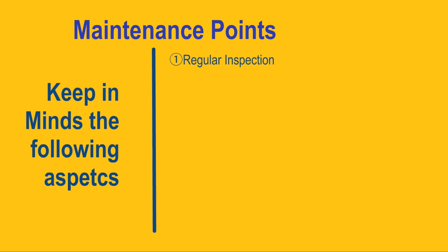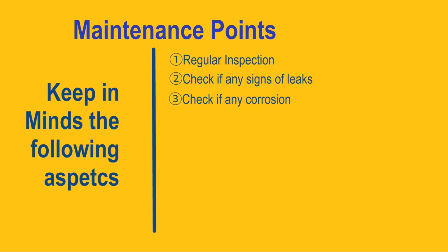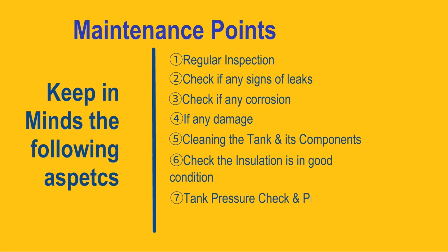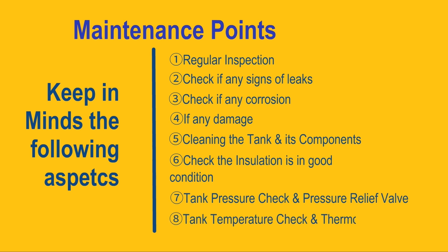There are a couple of maintenance points we have to keep in mind for the buffer tank, like regular inspection: check for any signs of leaks, and for any corrosion or damage. Clean the tank and its components whenever required or based on the schedule. Check that the insulation is in good condition. The tank pressure and pressure relief valve are to be checked. Tank temperature and thermostat are also to be checked based on the schedule.